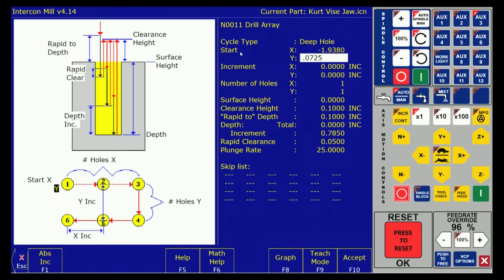0.0725. Good. So in that case, would that be a way of shifting the origin? No, would not. If we wanted to move in Op2, we noticed we weren't breaking the edge evenly, we wouldn't come into the tool path and change it. We would go into our work offset because all of our tool paths would need to move to line up with those existing paths.